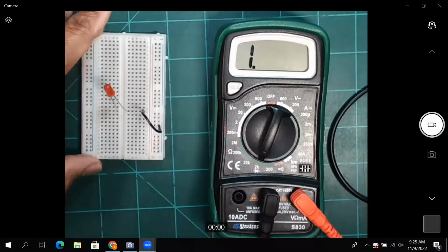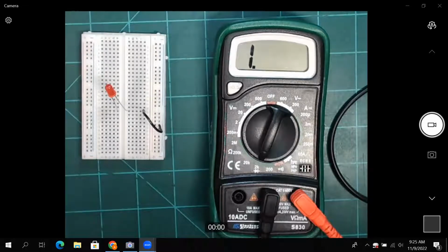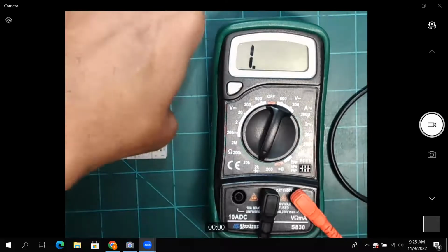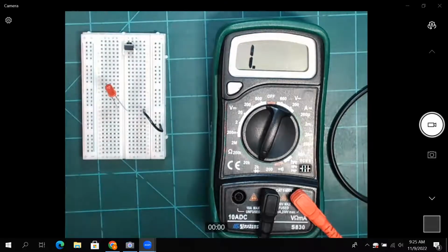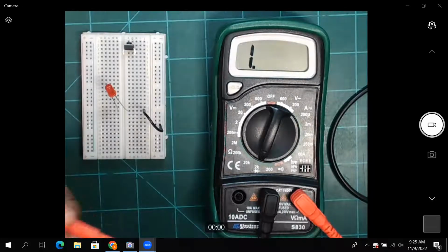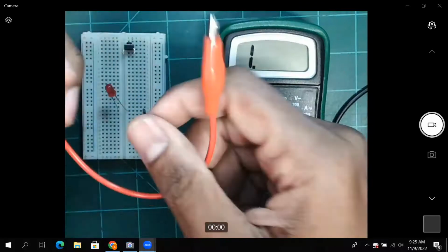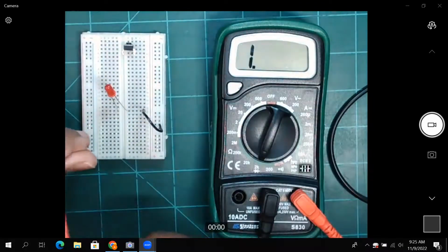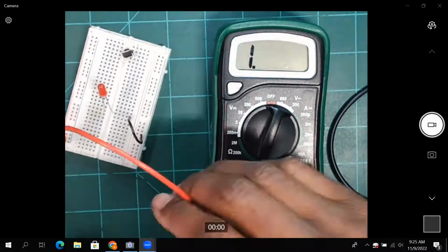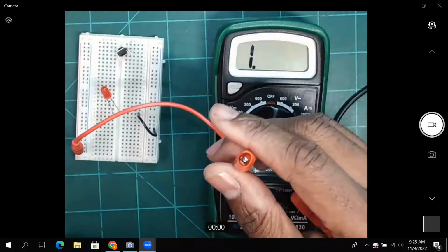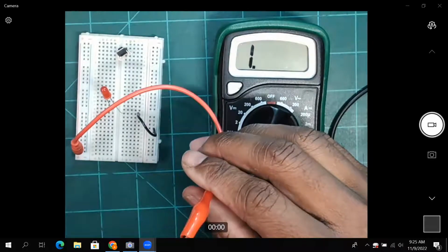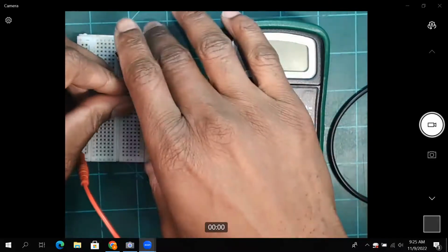Okay, so it's going to ask you to add a switch, and we don't physically have a switch, but you do have these little push buttons in your toolbox. Okay, and so what I'm going to do is build a circuit. Make sure that you strip a wire. Take your red wire, strip both ends, and then you're going to put it into your breadboard, and the other end of your wire, you're going to clip it to your power supply. And we covered this in our last class meeting.